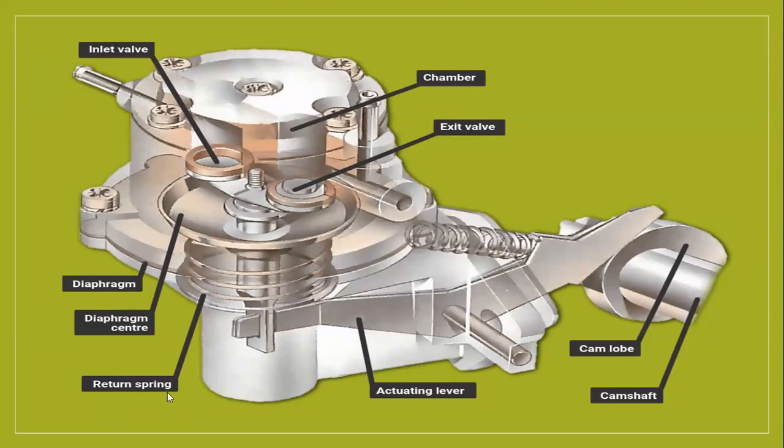The return spring will help you to move to the normal position. Then the cam will push down, the return spring will come up, then the cam will push down again, and automatically, continuously, fuel is flowed by this fuel pump, right?